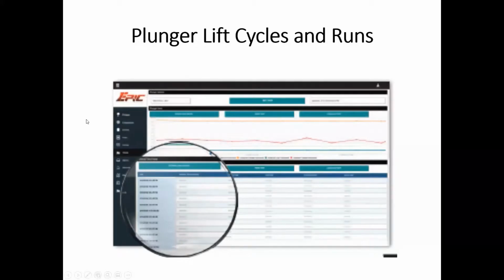Each cycle should be consistent with fluid load on top of the plunger before arriving. Cycle times should be consistent as well, with typical times being within 1 minute plus or minus of each other. Now, deeper wells will have a larger spread on that. So if you're trying to lift from 15,000 feet compared to a well that's at 3,000 feet, it's a little different. There's a lot more variables that go into lifting a plunger. Arrival and failures should be logged daily to ensure proper optimization.